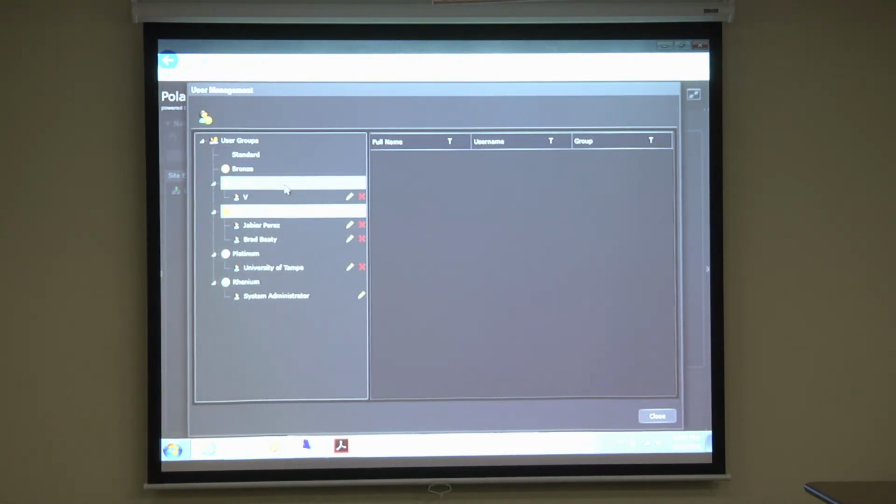And then the IT? Now for Robert, he's not gonna be really doing the program, he's actually HVAC, but the HVAC controls could later on be integrated with the lighting. He wouldn't actually be mapping out lights, but let's say he wanted to check something with the HVAC controls off the lighting. We use what we call BACnet, right? So this device system here exports points, because it uses an IP-based system, so they can pull the points and its name.